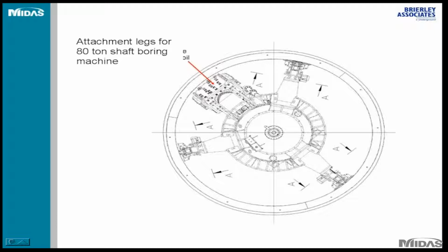But what we did, we had to add a cast-in-place slab around the area of the breakout or the launching of the TBM. So this is a special, separate design. We had to design an additional wall so you can have enough resistance or strength to resist the induced forces. Actually, the cast-in-place wall took almost one-fourth of the perimeter to build.